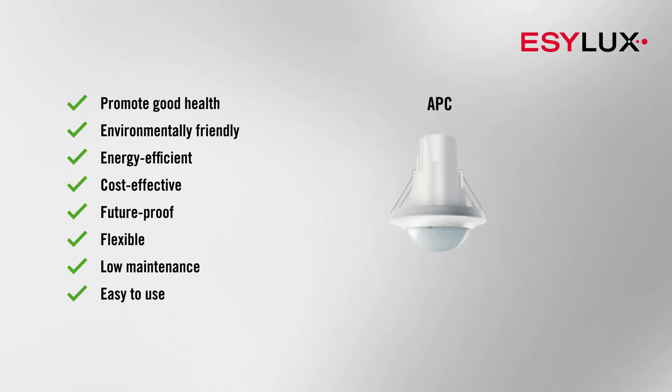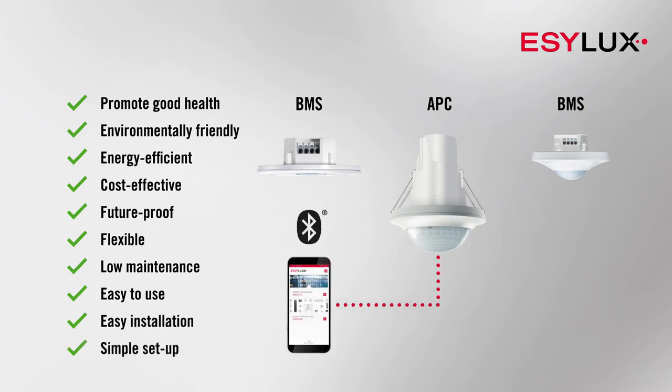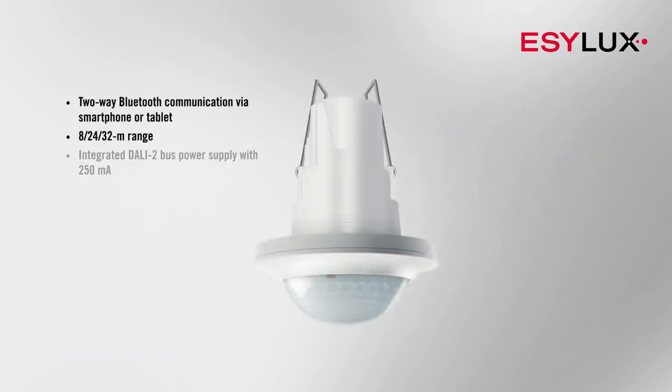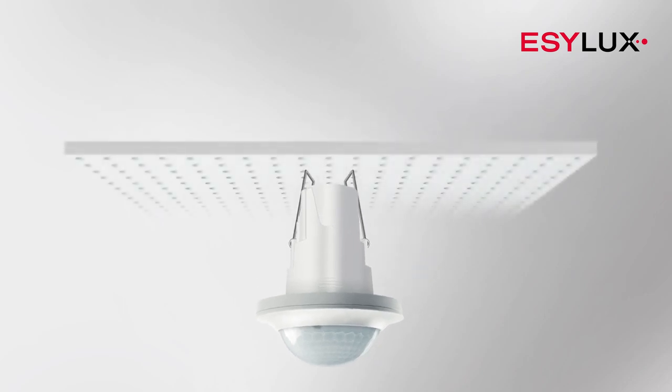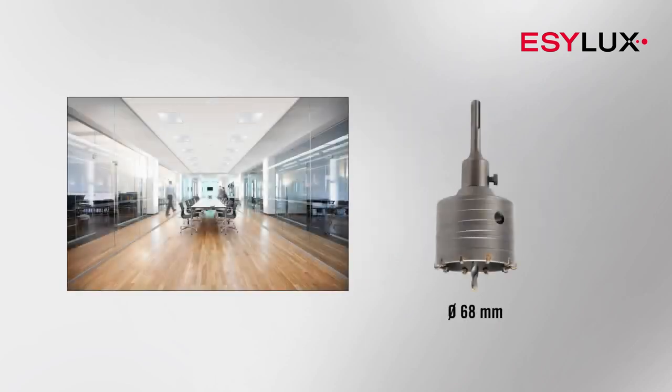Using APC presence detectors as controllers and supplementary BMS presence detectors as input devices that are easy to install and can be set up using an app. The APC presence detectors of the compact series support two-way Bluetooth communication and feature an integrated bus power supply. They are optimized for false ceilings and can be installed without any additional accessories. And for suspended ceilings, you simply need a standard drill bit.